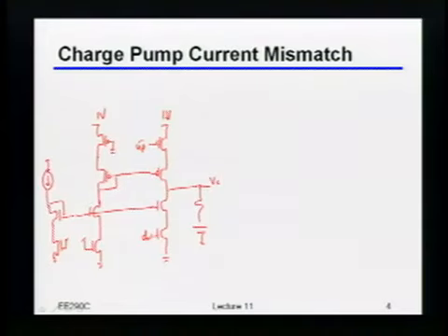So let's say we use a reasonable V star. Let's say that's 100-ish millivolts or maybe 200 millivolts, somewhere in that ballpark. That would basically say that you want this to range from something like about 100 millivolts up to maybe about 900 millivolts. That's maybe a little bit aggressive, but somewhere in that ballpark, right?